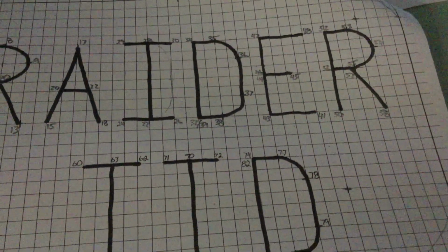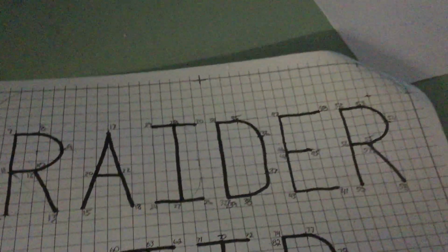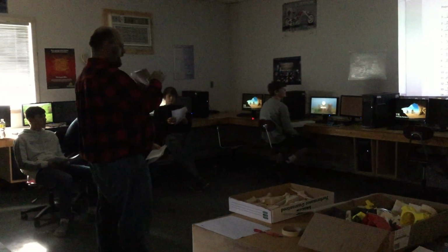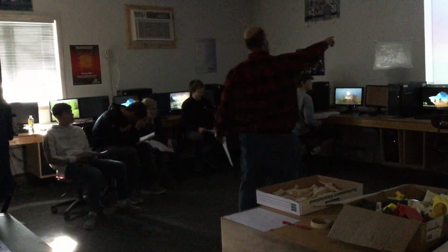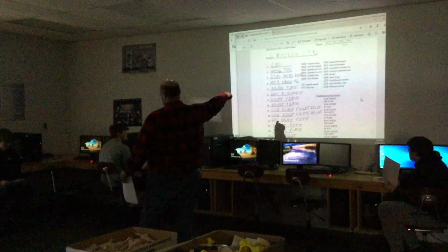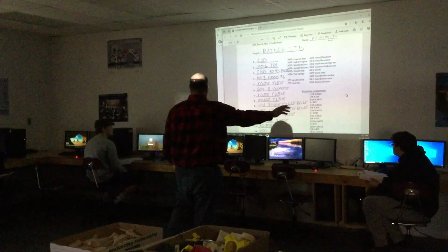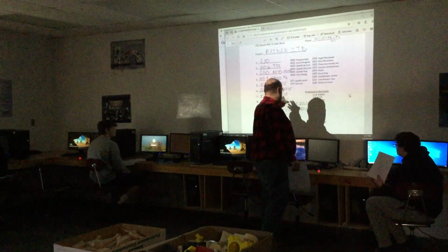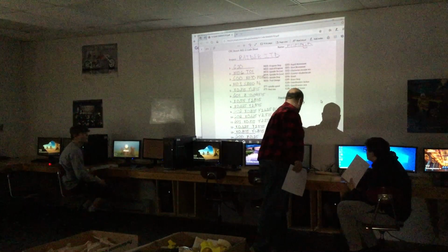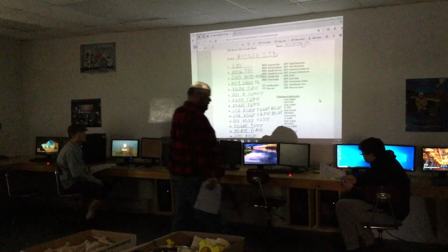So what's the Z coordinate? Yep, that's the one over top that's going to tell it the depth, up and down that way. When I set this, I wrote out what each step is. So step 4, I just told it to go to that spot. Or excuse me, it's step 5, so we're at X 3/8, Y 1 and 7/8. That's the other thing that's going to be tricky: you can't put fractions in. On this part, and I think it's also on your paper, I put all those conversions.